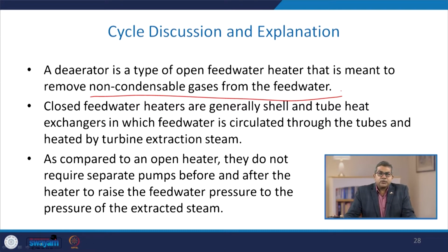So, the closed feed water heaters are generally shell and tube heat exchangers in which the feed water is circulated through the tubes and heated by the turbine extraction steam. If we compare with the open heater, they do not require separate pumps before and after the heater to raise the feed water pressure to the pressure of the extracted steam.